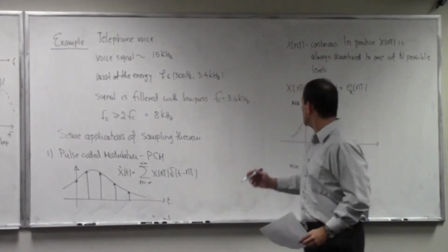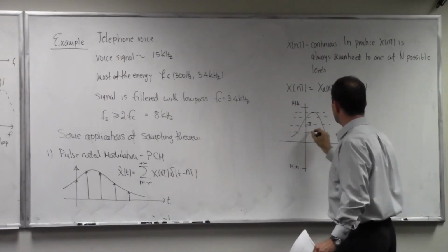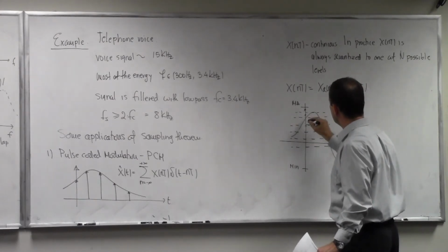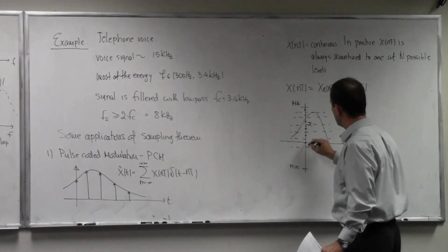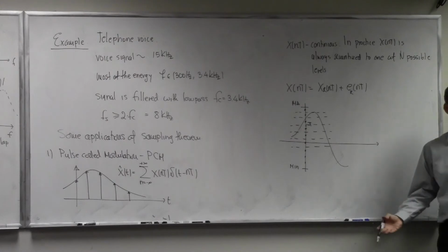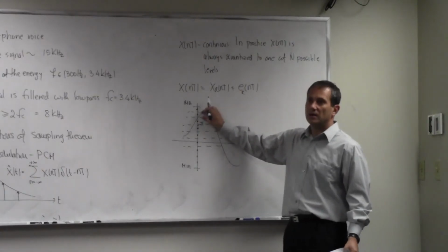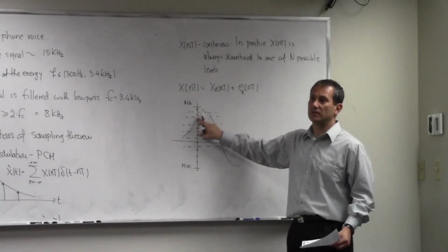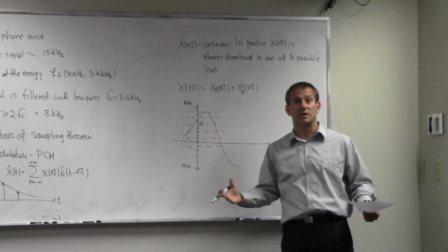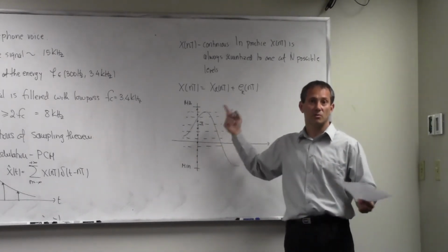So the way around it, what we do in practice, is we take this interval and divide it into a certain number of subintervals, and then we declare a single point inside each one of these intervals, and these are my discrete values. How many discrete values do I have? It's again a design parameter, something in my control. But whatever falls within a given interval is approximated with the center point of that interval, right? And in the process, we make an error in representation which we call quantization error. The size of this error is within our control. The more intervals we have, the smaller the error is.